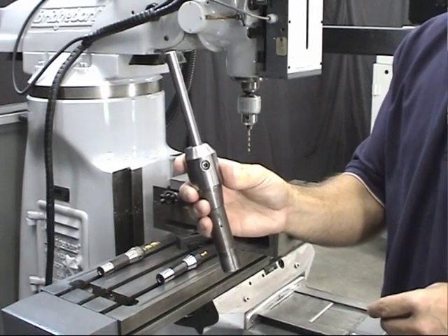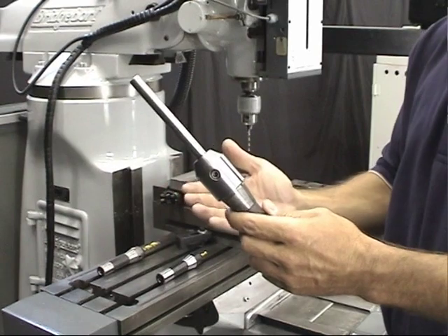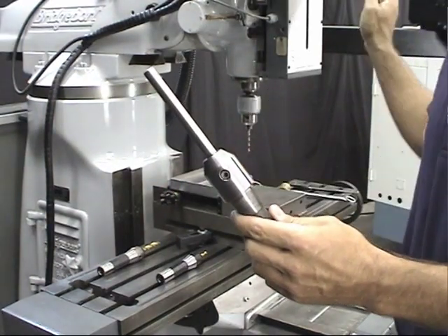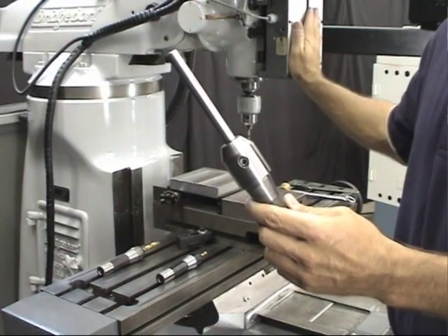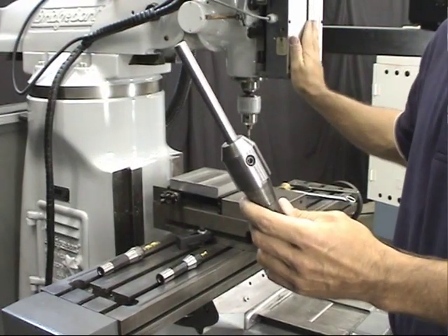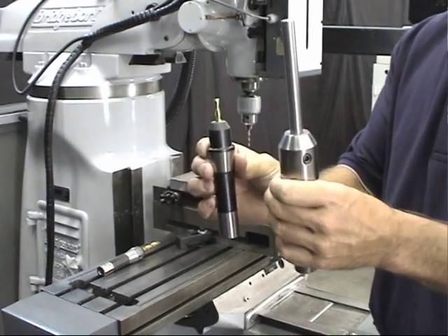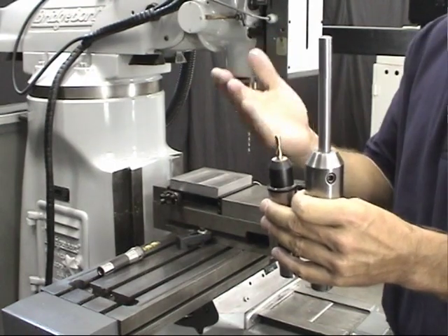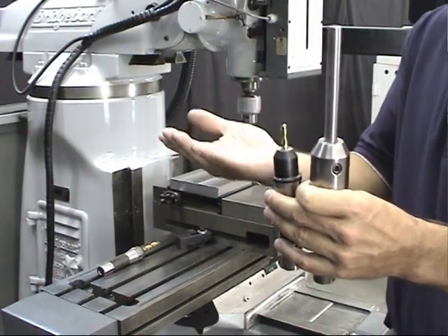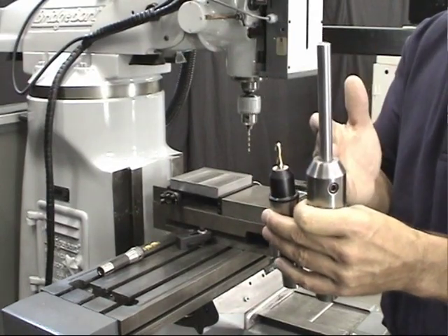Okay, let's start with the reference tool. How do I know how long to make my reference tool? Well, a good rule of thumb is to take the amount of Z-axis travel you have. In this particular machine, it's about 4 1/4 inches, and add it to the shortest tool that you're going to use. So my reference tool is approximately 4 1/4 inches longer than the shortest tool that I'm most likely ever going to use. That's just a good rule of thumb to get you in the ballpark.